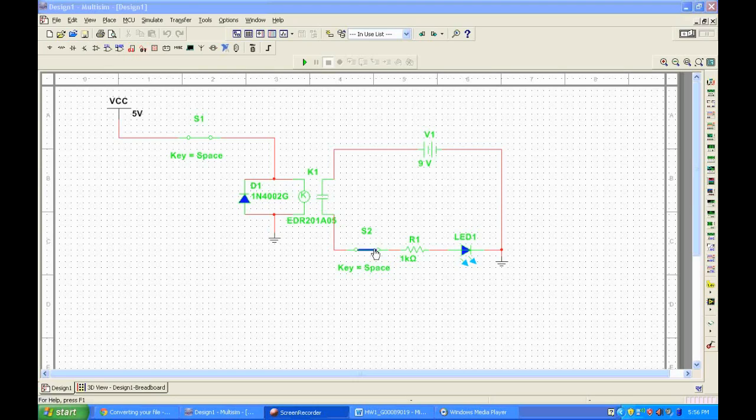So at this point, one more thing before I activate the circuit, I would like to note that this switch here is a manual shutoff switch, because if this circuit was built physically and we had the PIR sensor here, once it pulsed to the relay, we would have it latch and the light would remain on continuously. So I included a switch on this circuit here that we could open up in order to have the light shut off manually. So at this point, I would like to demonstrate how the circuit would work.